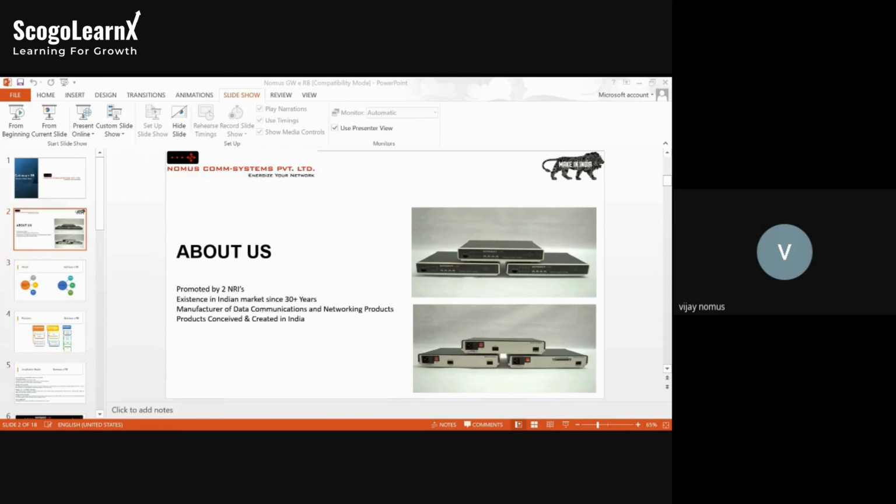So coming back to the gateway RB, the rear panel will have the power on/off switch for powering the device on and off, and one IEC type power connector and fuse holder. We are providing one fuse holder for replacing any fuse. Whenever you insert a power cord, there is the fuse picture, that is a holder. We have to remove that holder, and you will find two fuses. One is inside, that is the working fuse, and the other fuse will be the spare fuse.